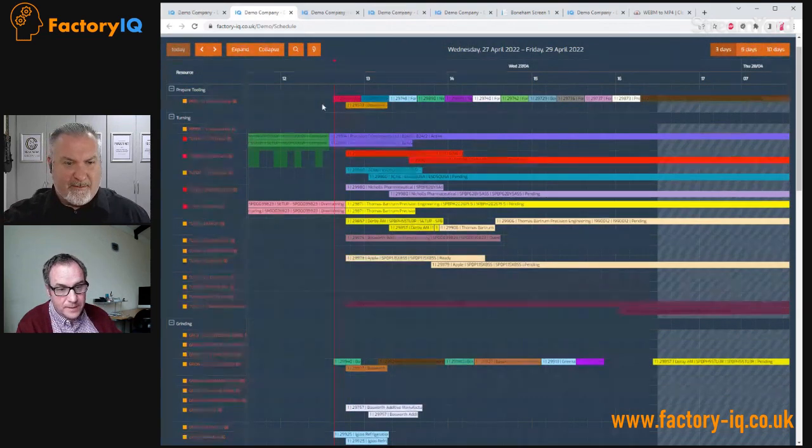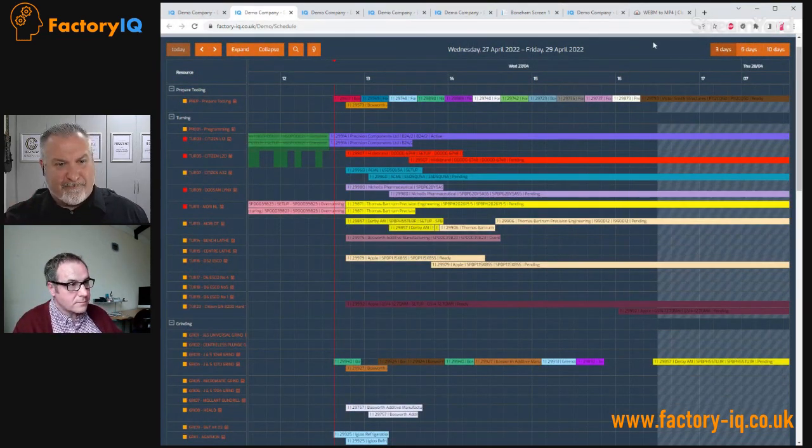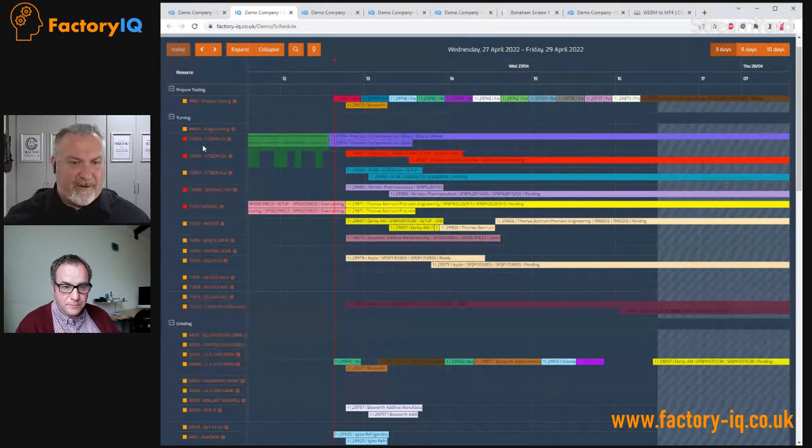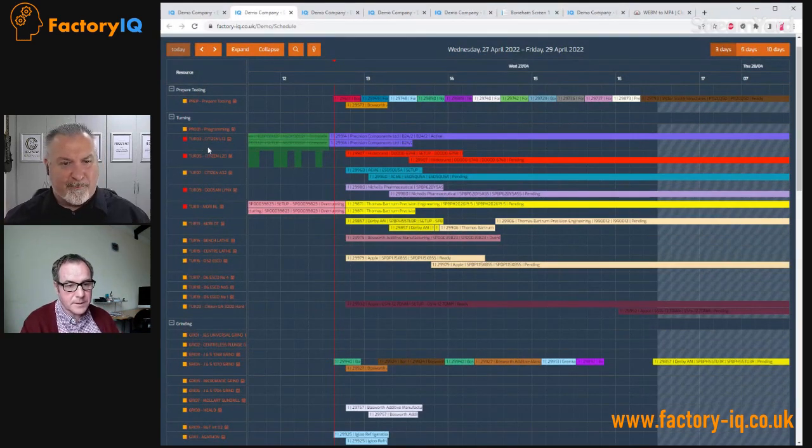This for me is the big thing around seeing the hidden factory. We suffer with a hidden factory. Having this real-time data enables us to see these gaps in production and then question and challenge what's happening around that, and understand the root cause. Is it changeover, is it breakdown, is something happening, have we got setup issues, are we getting adjustments in setups, or adjustments as we're going along, tool changes? This allows us to see the downtime. So what Peter's just seen is probably that for that space of time we've been 50% down and 50% up, which for me is not good enough, and we can go and investigate.